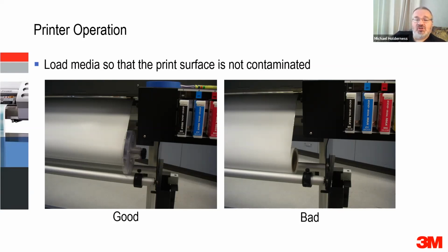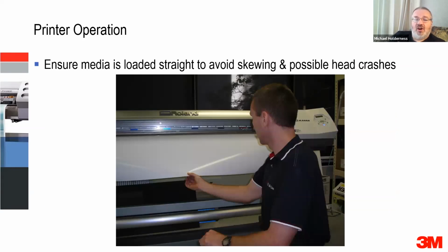So load the media so the print surface is not contaminated. You can see my colleague Chris from Australia, he took a number of these photographs for me. We gathered together on this presentation, and so you'll see Chris in a couple of places in here. Ensure the media is loaded straight to avoid skewing and possible head crashes.